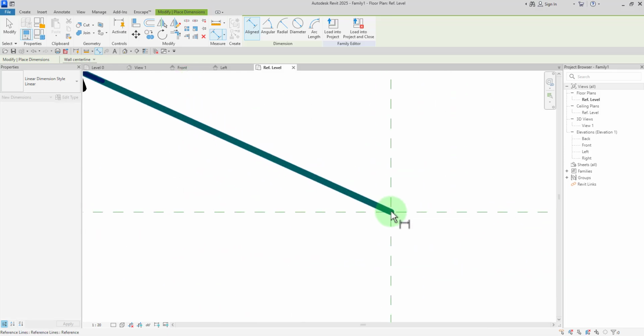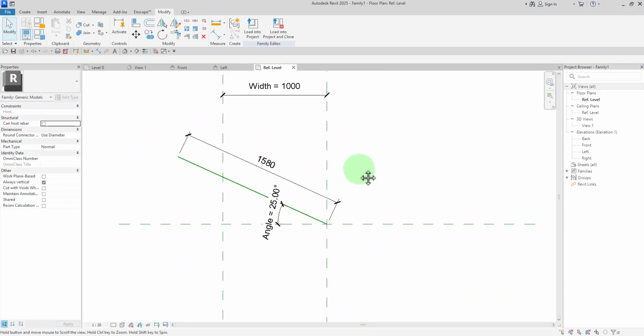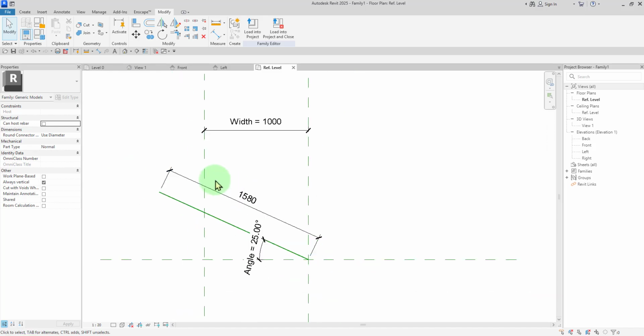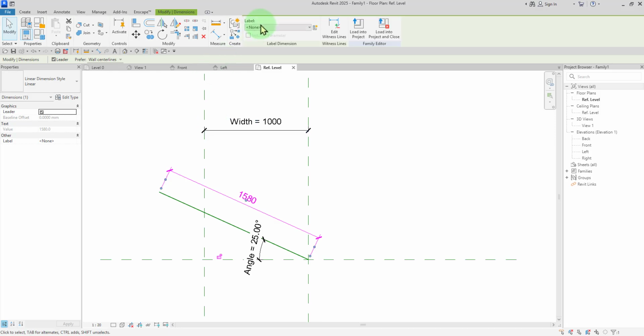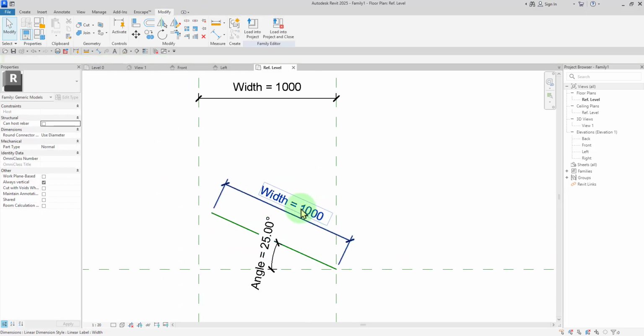the tip right there. Click on tab, and it's found the tip right there. So I'm going to click on that and lift that dimension up right there. And what I'm going to do is change this dimension to be equal with my width in there. All right, so I'm going to click on this, and then click on the drop down menu right there, and then change that to also look like my width in there, which is perfect. So from here to here is the same 1000 millimeters as my width, because I want my door to close with the same dimension in there as well.